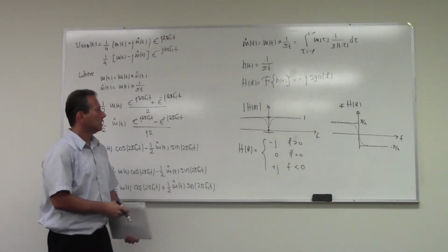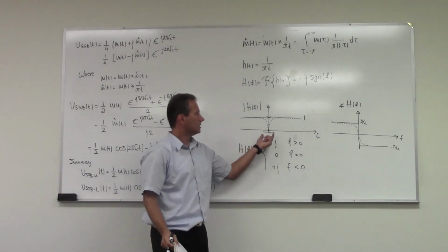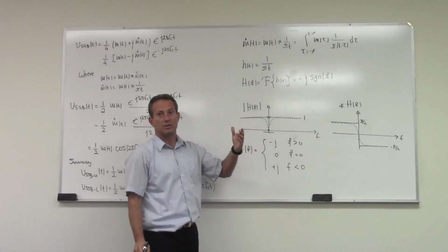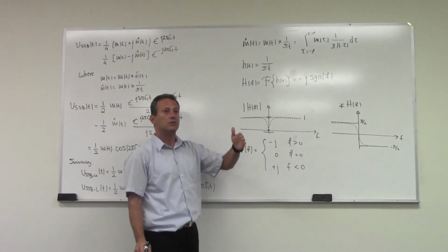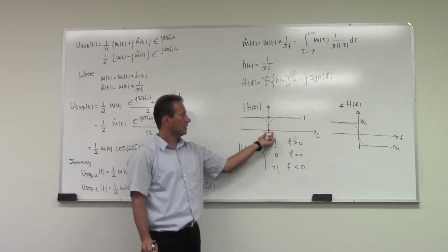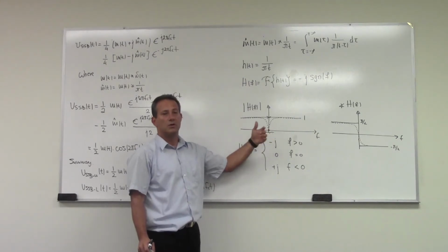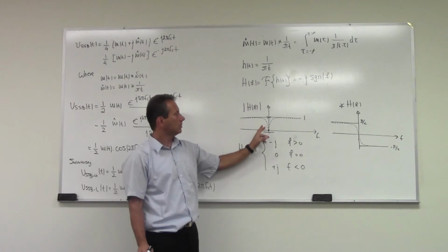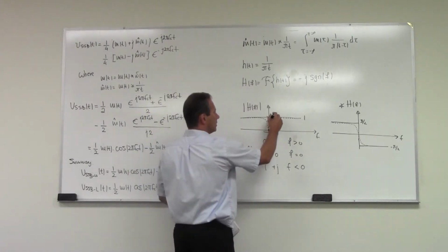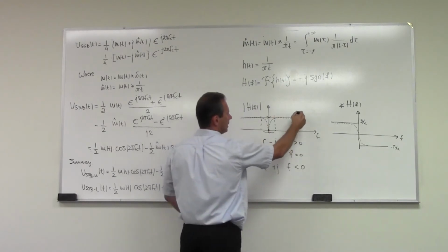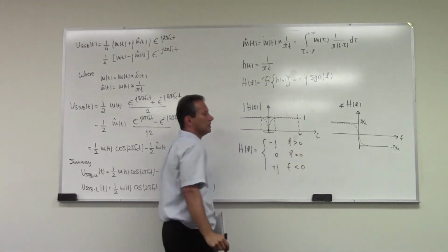If you think about voice, what is the spectrum of the voice? We can say telephone voice starts at about 200-300 hertz. So in this region from 0 to 200 hertz, whatever the frequency response of this filter looks like is not very relevant. What you need is, if this is the lowest frequency of your signal, that's where this needs to be approximately 1, and then this is your W, where the signal ends.